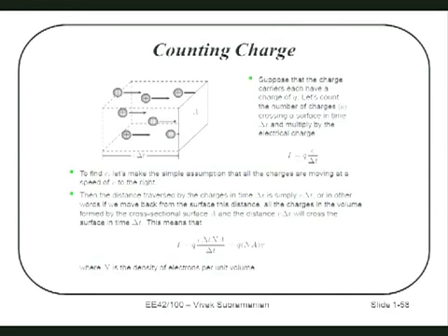So we multiply by the area of the plane to get into the right units. And so we then have I is equal to Q times V times delta T times N times A over delta T. And so what this says is I now have a way of, given a box with a certain density of electrons and a certain velocity of electrons, I can figure out the current.